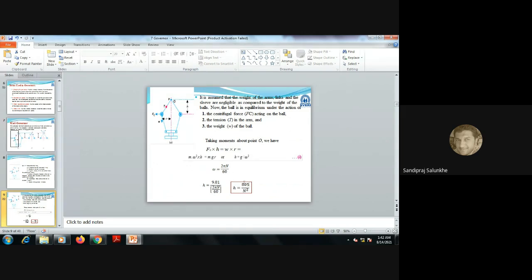895 divided by N square, capital N square. Now you can ask me, what is this 895? N is nothing but the speed of engine. Okay. Now this 895 is a constant. From where it comes? Because when you are going to calculate omega, omega is nothing but 2 pi N divided by 60. Whereas g, that is the gravitational acceleration, which we are going to account when m is converted into W. So this g and this 60 is multiplied, divided by this 2 pi. That value is 895.